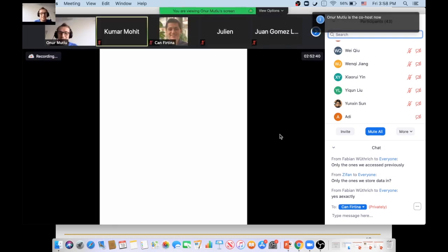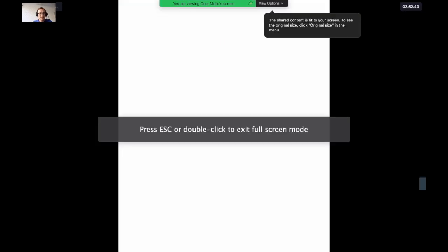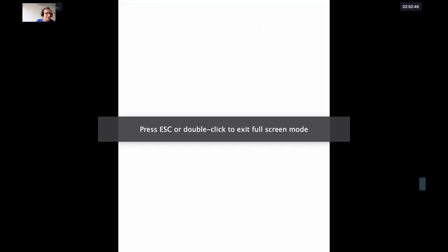Whiteboard. Okay, can you see my screen? That's good. So basically, what we're really trying to do is, okay, I don't want to see myself on the screen. What we're really trying to do is, so we have retention time bins, right? So everything that needs to be refreshed every 64 milliseconds. And everything that needs to be refreshed every 256 milliseconds. And we have a set of rows for this, right? Let's say row 1, row, I don't know, 50, row 5,000, dot, right?